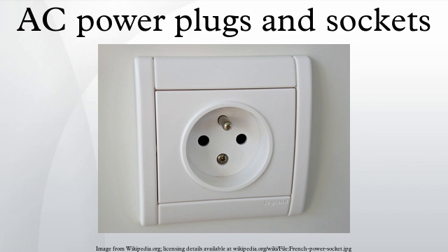Single-phase electric stove plugs and sockets. The plugs and sockets used to power electric stoves from a single-phase line have to be rated for greater current values than ones for three-phase system because all the power has to be transferred through a single line. Electric stoves are often hardwired to the electrical supply system, connected to the mains with an appropriate high-power industrial connector or with non-standard high-power proprietary domestic connector. In Russia, an electric stove can often be seen connected with a 25 to 32A connector.